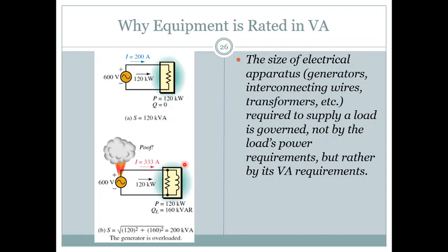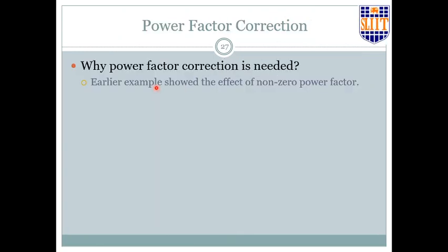So that is why the devices, particularly the industrial devices, are rated in volt amperes, that is the apparent power. If you give this much voltage, the standard voltage, if it is single phase 230 in Sri Lanka, it may be 3 phase, whatever it is, it is marking the current. You can calculate the total RMS current that will be drawn. But keep in mind, part of it is returning, but you can't just forget about that part. You will have to consider that as well. So that is why the rating is given as volt amperes instead of watts.